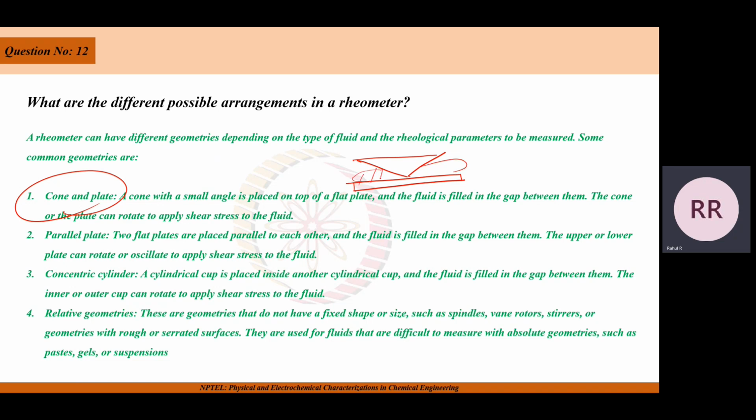So here the fluid is filled. The cone or the plate can be rotated to apply shear stress to the fluid. Either the cone is rotated or the plate is rotated, so that the fluid experiences shear stress, and then the corresponding rheological parameters will be measured.